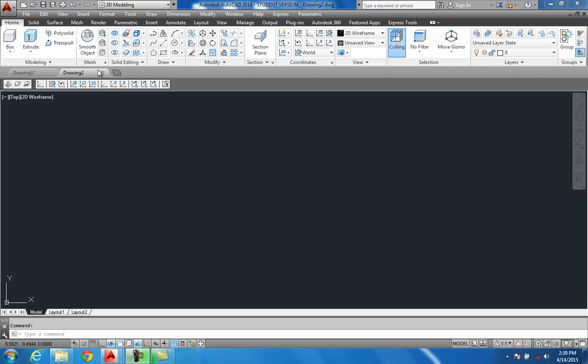So we'll go in here and we'll do some work. First thing I always do is lay me a line in there. It'll be my axis line. I'll use this as my axis. Or, to be honest with you, probably better off if we went to make us a line on 0,0,0, enter, 0,0, enter, and I'll just stretch it across here.